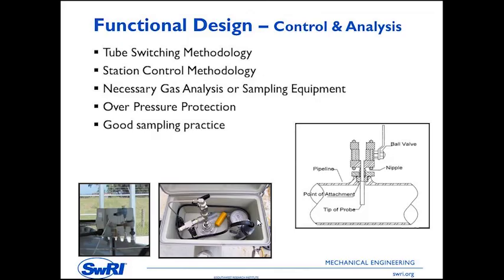Particular points of interest would be where this hydrate formation curve crosses each of these saturation points, and you have opportunities for hydrate formation. You can see that these hydrates could form considerably before you get to a freezing point of water. There's a lot more discussion that could go along with that consideration, and I just wanted to mention that there.